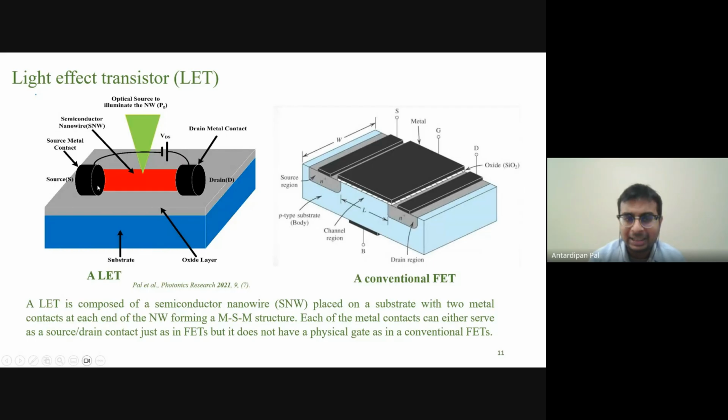So if we have asymmetric contacts, that can minimize the dark current, because at one side it will be ohmic, that's fine, the carriers can tunnel, but on the other side, due to the Schottky contact, the potential barrier would increase for the carriers. The carriers will see a high potential barrier. That means they cannot cross that. Even if they're injected, they cannot pass into the other side. That means the overall dark current will be much reduced.